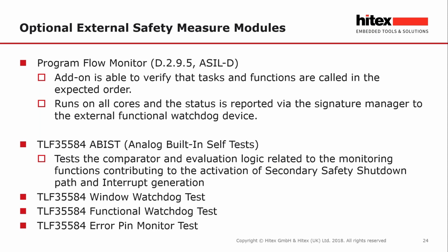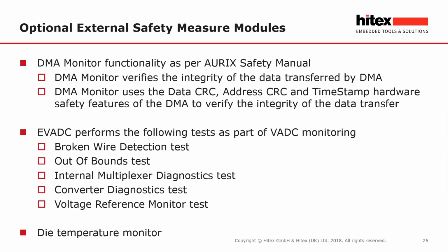The TLF35584 ABIST is also available, and this is testing the comparator and evaluation logic for the monitoring functions that overall contribute to the activation of the secondary safety shutdown path and interrupt generation. Also, the window watchdog test and the functional watchdog test and the external error pin monitor test is included. There's also an optional DMA monitor. Another one which almost everybody seems to need is the